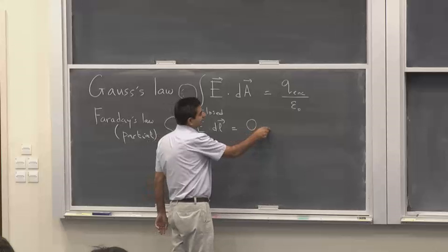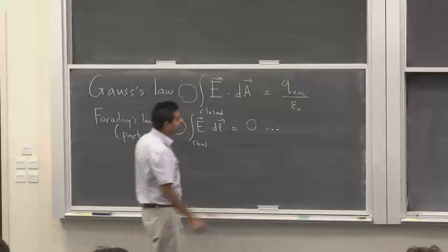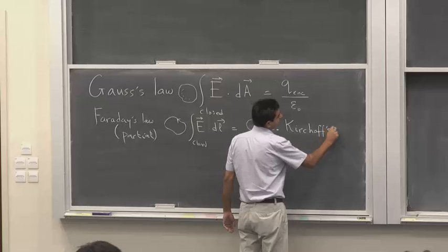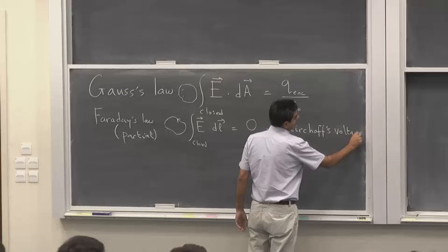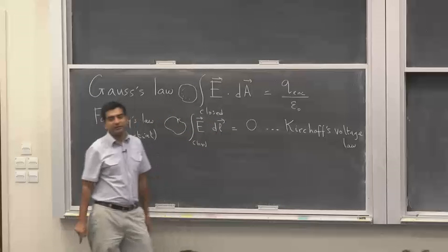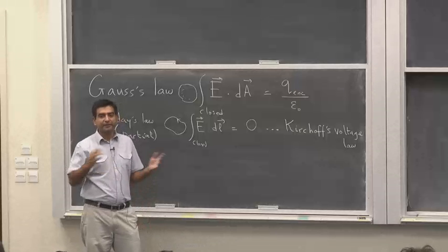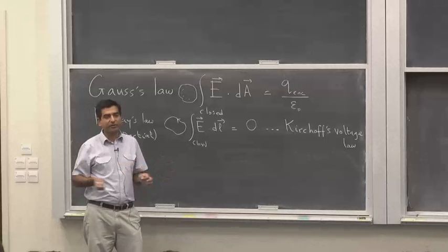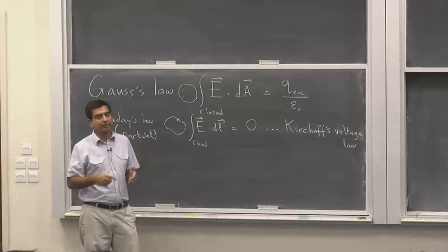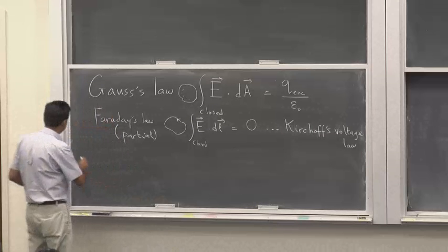When you talk about electric circuits, this law is just akin to Kirchhoff's voltage law, KVL, because as you can well imagine, this is a potential difference. If you go around a circuit, which is also a closed path, then the difference in potential from the starting to the final point is 0 because the final and starting points coincide. So around a loop in a circuit, the sum of voltages is 0. This is what we've been discussing so far.